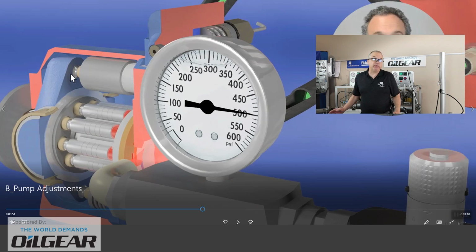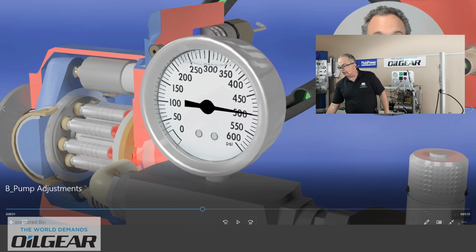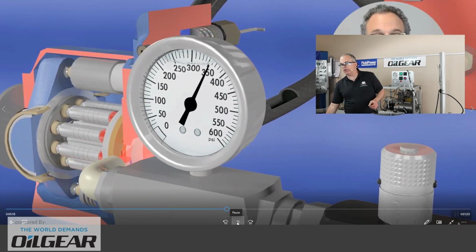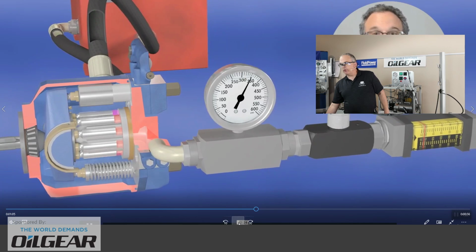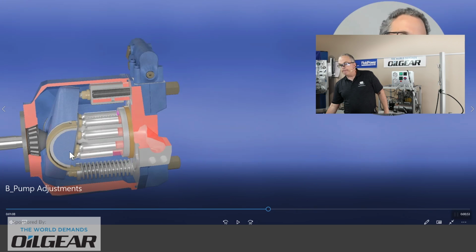And anytime that pump gets to that zero angle, due to internal leakage in the pump, that pressure will start to fall a little bit. Then the spring in the compensator will close up the pressure compensator once again, and a device called a bias spring or a bias piston down at the bottom in this pump will try to drive that swash plate back on stroke. There's a bias to this basic pressure compensated pump that says, hey, I'd like to go back on stroke to full production if I could. Okay, so that's the spring there at the bottom, which in this case also includes a piston. There we are, back on stroke.